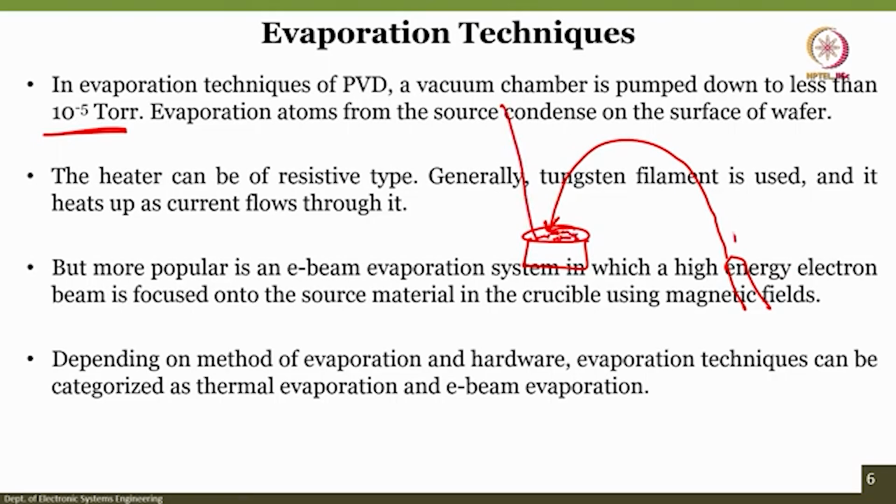But the way it travels and forms an angle, all these things are not so easy. We need to understand where the magnets are placed, how the accelerator works, how the electrons are accelerated further, and how the bending works because of the magnetic field. All these things are important. You have a spot beam, you have a raster mechanism for the beam. So there are different ways of using an electron beam evaporation system.